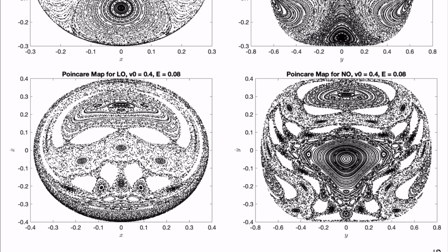And if you look at the one for the NO, you can see that there's a really nice, interesting structure going on here. You have points where you have a single fixed point, another fixed point here, and these are surrounded by 3, even maybe 4, 5, 6, 7, many fixed points actually. There are many different fixed points that arise here. This is due to the bifurcations in the dynamics leading to different types of internal resonances, different types of nonlinear modes that appear due to bifurcations in them, and so forth. And then they're all surrounded by these chaotic regimes, such as the ones shown here.